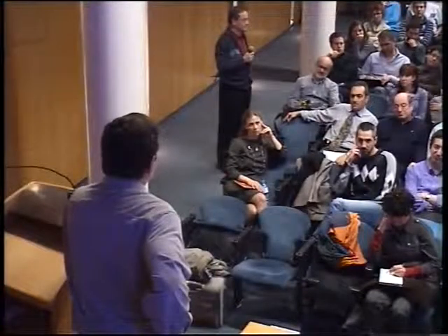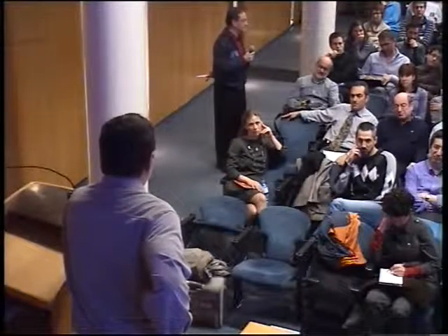Of course, I'm not really sure that I know all the answers, or even half the answers. The first comment is that if you divert water, you're going to divert sediment. And it's very, very hard to divert water, but not sediment. If you can take the water from relatively high up, then you're collecting finer sediment. But the fundamental way that rivers develop their floodplains is through overbank deposition of sediment. So it's a natural process.